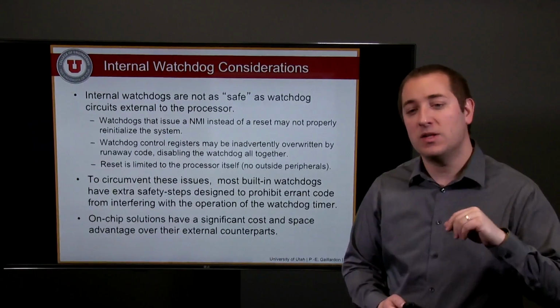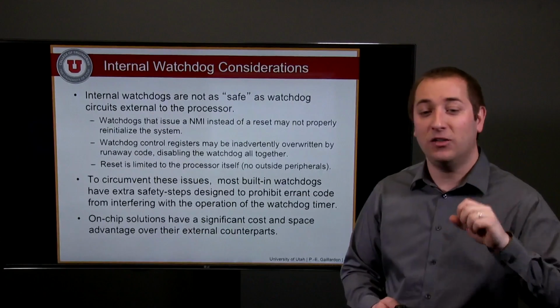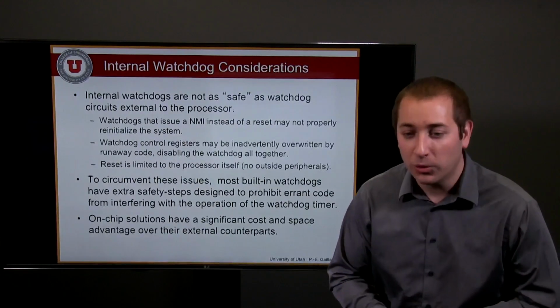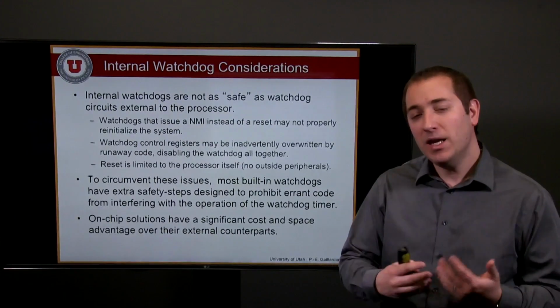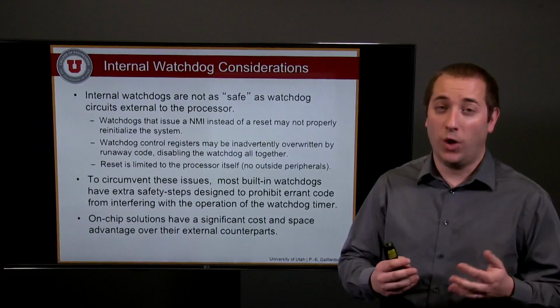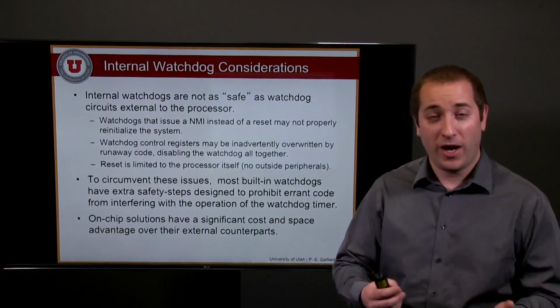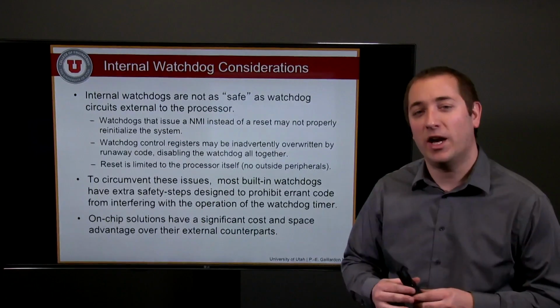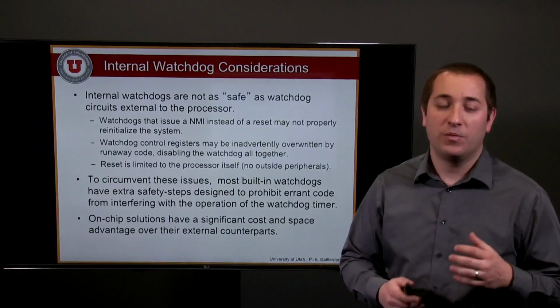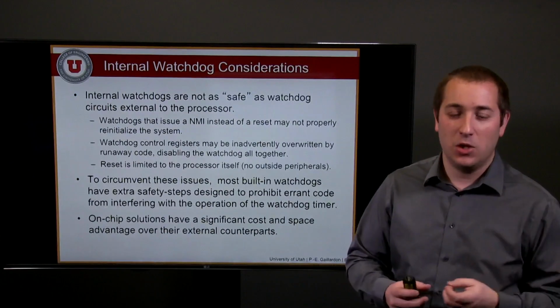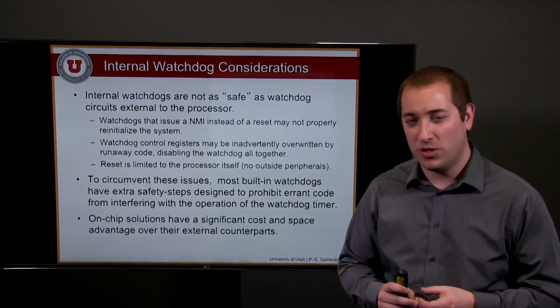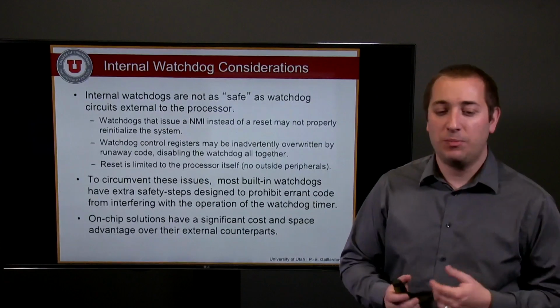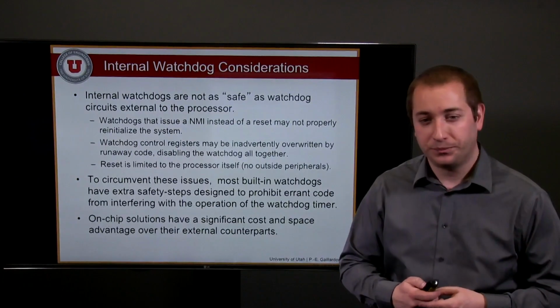Even though it is slightly less safe than an external watchdog circuit, microcontroller manufacturers do have extra safety steps that prevent those kinds of operations. So nowadays, using internal watchdog timers is a pretty cost and space efficient solution.